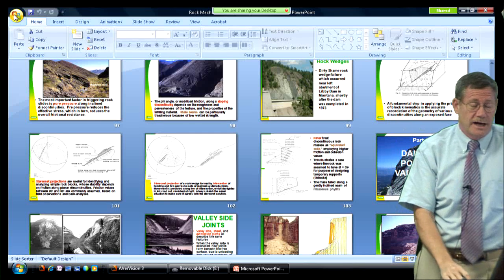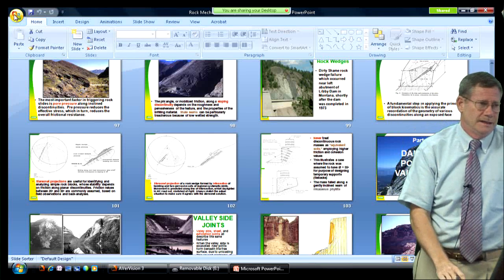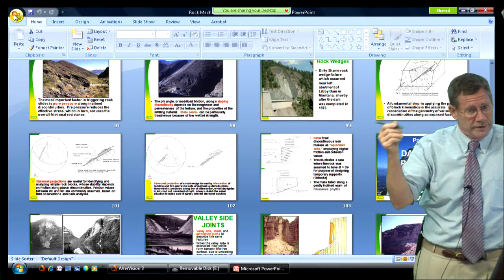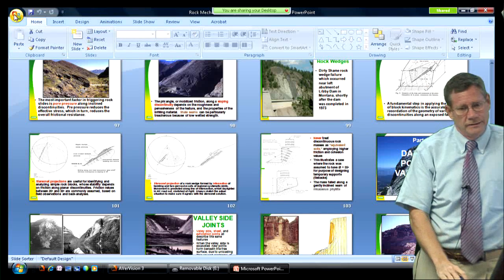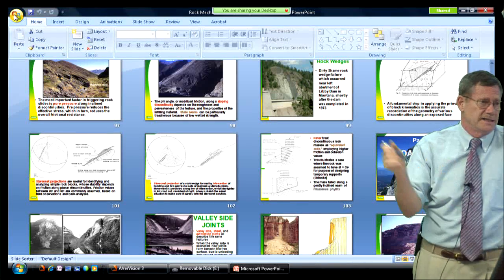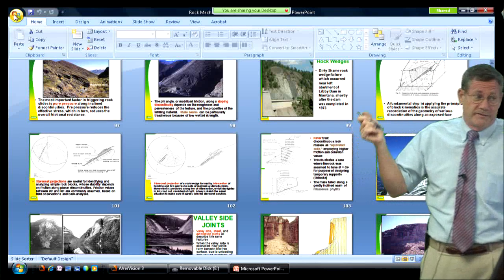If you're going to scout and scale a slope, you have to do it continuously, especially if you have people working under it. This happened at Hoover Dam too. We had some serious rock slides that did a lot of damage. A number of slides have landed on the powerhouse roof and other places, and thank God we haven't killed anybody yet.